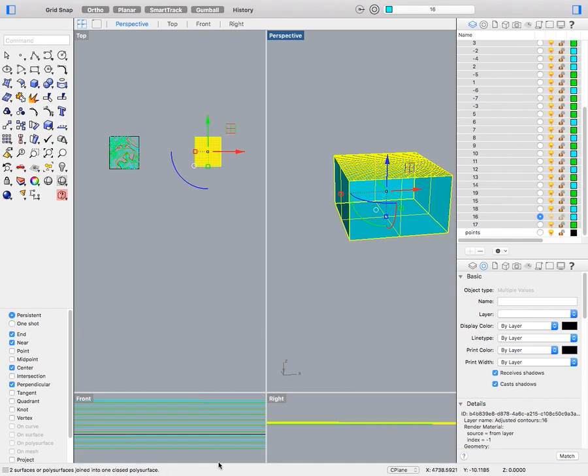So see down at the bottom it says one closed poly surface. You want to make sure that your terrain model is always in a closed poly surface, otherwise you have weird openings and things in your model, which further down the line when you do CNCs or 3D modeling, or 3D printing, it always needs to have those closed surfaces or closed poly surfaces. Right now it's not too important for the actual laser cutting, but you will need that later on.